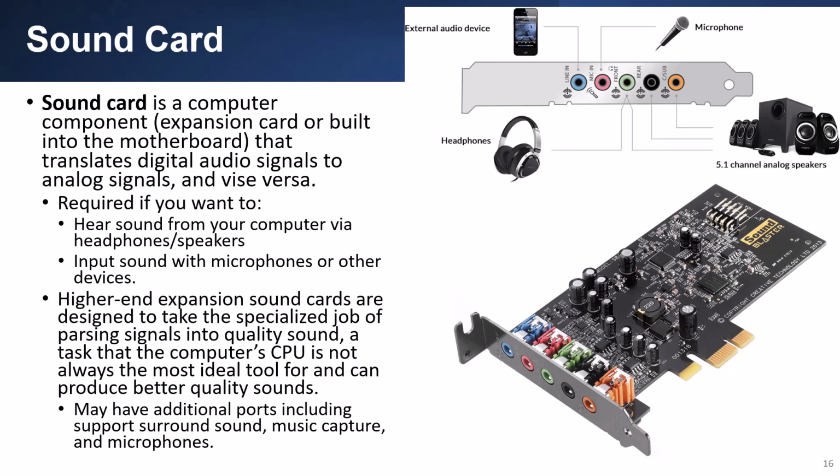A sound card is a computer component, either an expansion card or built into the motherboard, that translates digital audio signals to analog signals and vice versa. It's required if you want to hear sound from your computer via headphones or speakers, and if you want to input sound with microphones or other devices. Higher-end expansion sound cards are designed to take on the specialized job of parsing signals into quality sound, a task that the computer's CPU is not always the most ideal tool for, and can produce better quality sounds. You may also have additional ports including support for surround sound, music capture, and microphones.